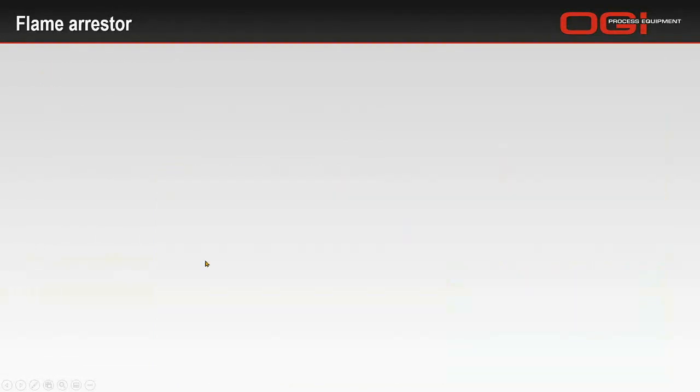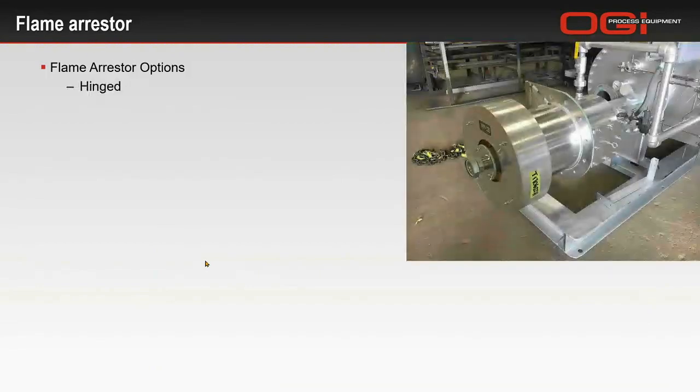And some typical options for flame arrestors include a hinged flame arrestor. This is nice for technicians who need to do burner inspections, operations, or tuning. You're not having to open up and take out this flame cell element, which actually gets really heavy on larger flame arrestors, and prevent it from damaging. So you just kind of open it up here.